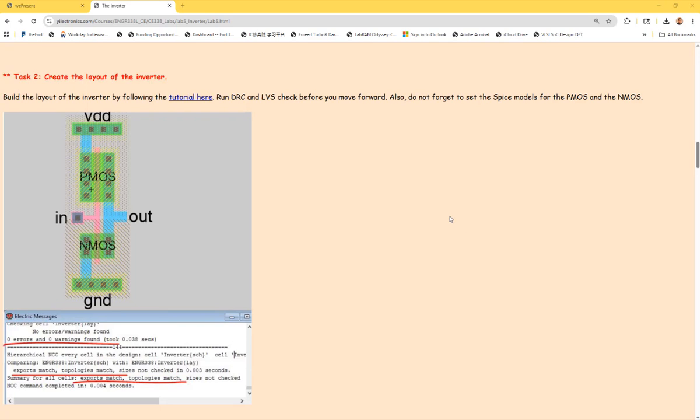And this is P plus, and that is why we connect it to ground. I think the component's name in the Electric VLSI library is called P well, because it's a P well tap. They just name it P well. It already has a metal one layer overlaid on top with the vias. So it's a P plus layer with vias and metal one; that's the component available in the library. Because you already have that metal one, you can directly right click and connect this one to ground, because it's metal. Same here, connect to VDD.